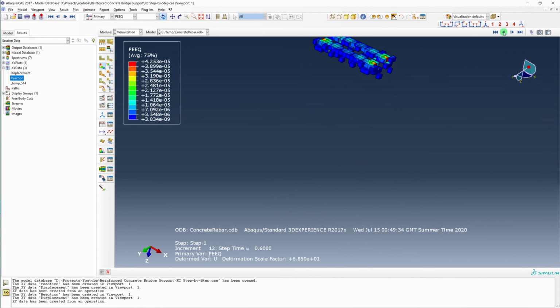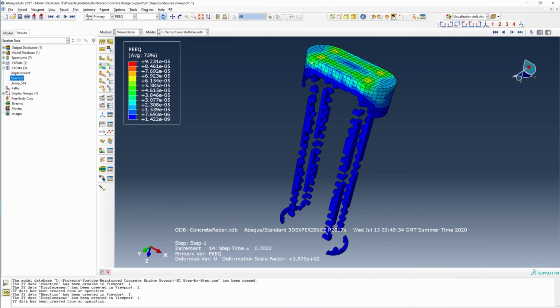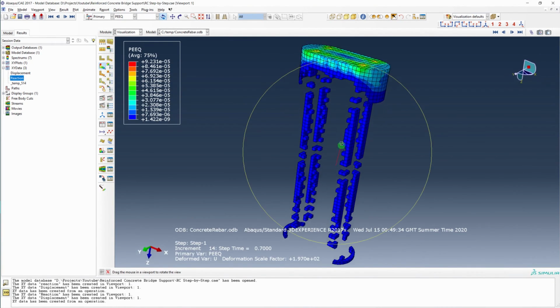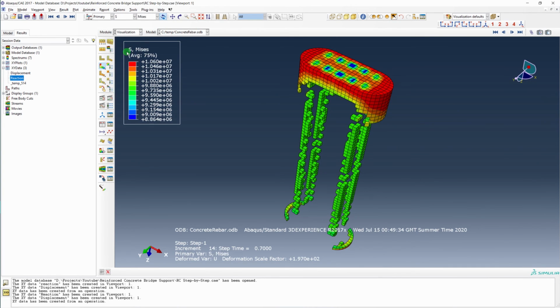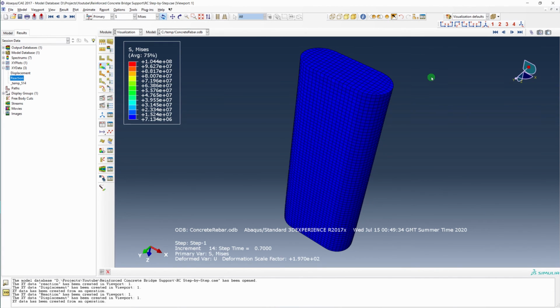So we do have yielding of elements before that. We can see it starts at 0.45. But it really isn't until time frame of 0.7 that we see it impacting the low displacement results. Just the yielding must be significant enough there to be visible, at least looking at that graph. Okay, go back to stress, and I'm going to show everything once more.